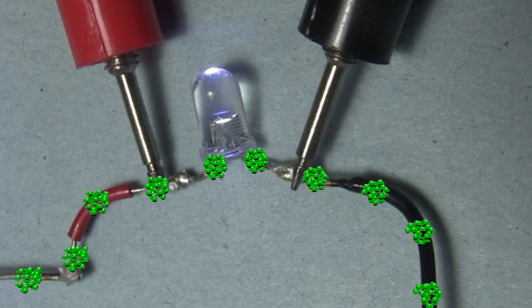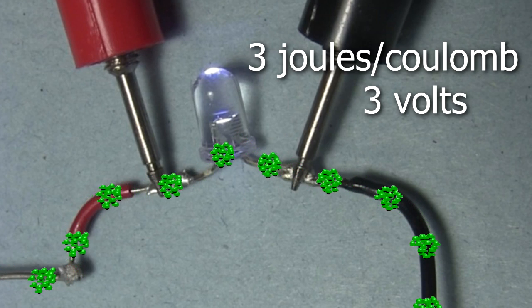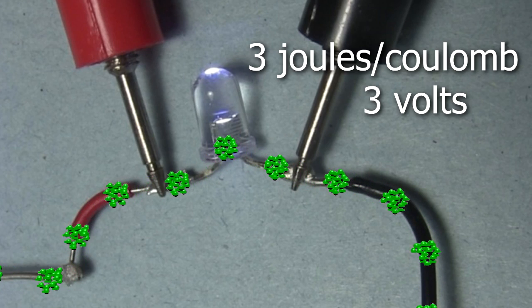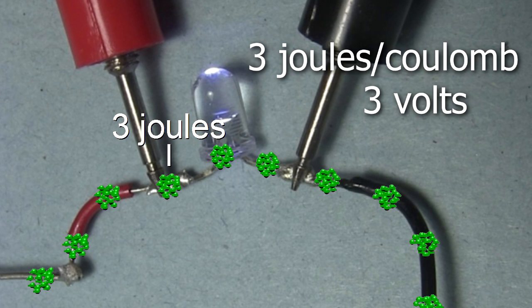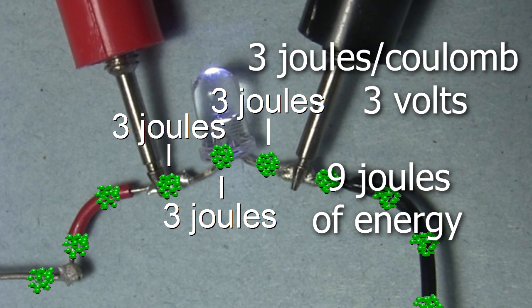Let's say this is what's going through the LED. And let's say that the voltage is 3 joules per coulomb, or 3 volts. If the voltage is 3 joules per coulomb, that means there are 3 joules of energy moving this coulomb of charge, 3 joules of energy moving this coulomb, and 3 joules moving this coulomb. That's a total of 9 joules of energy, but the voltage is only 3 joules per coulomb, 3 volts.